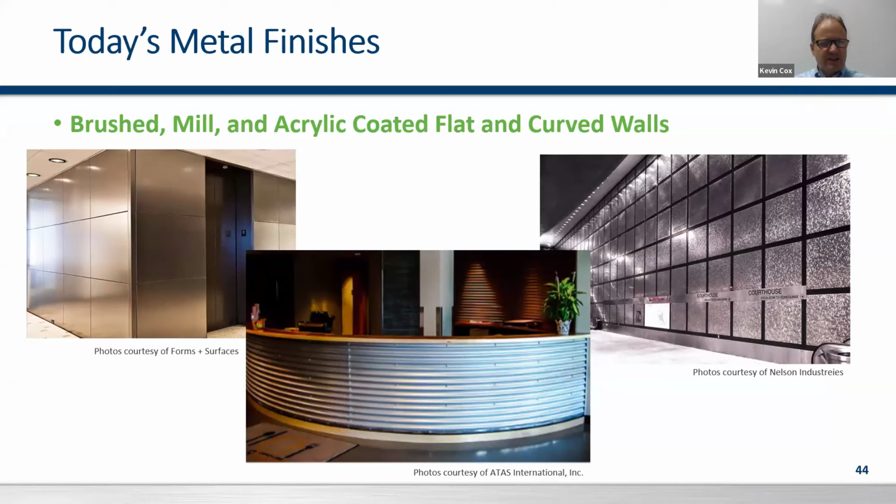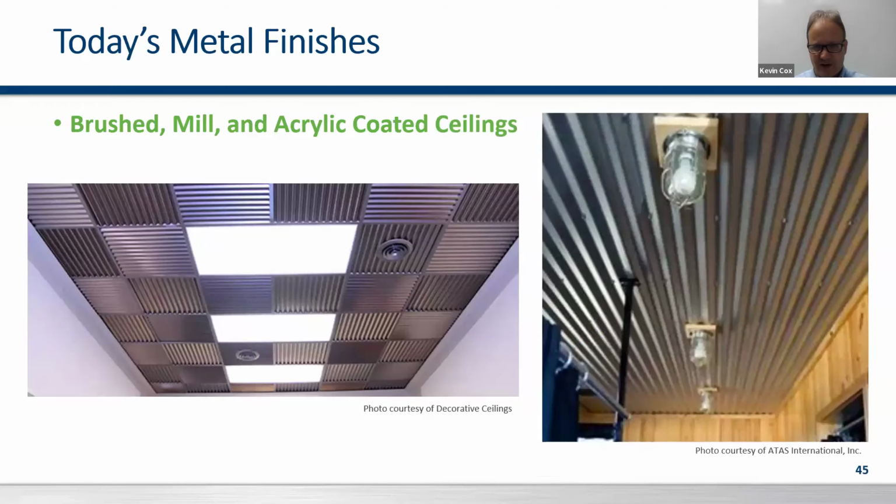You can always radius a corrugated panel along its corrugations. We kind of call it curving it the easy way, as long as we're putting it to a substrate. With the pyramid rollers, we can actually curve it the long way and get that long, nice arc out of it, and putting it under a desk and kind of creating a focal point.